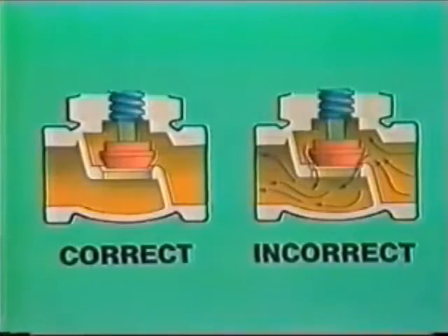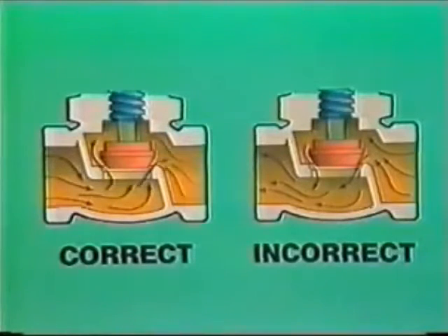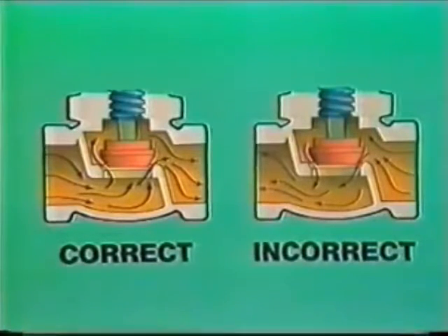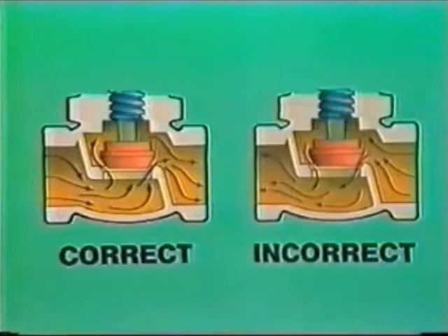A globe valve is usually set up for throttling so that the flow is from below the plug, which tends to open the valve. This provides a more stable operation and eliminates slamming or closing as the plug nears the seat ring.